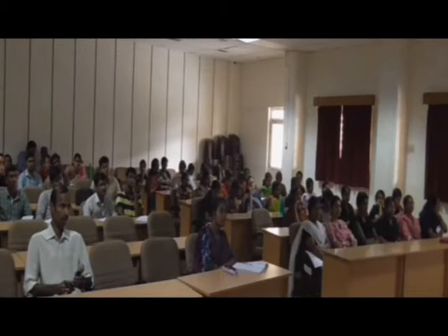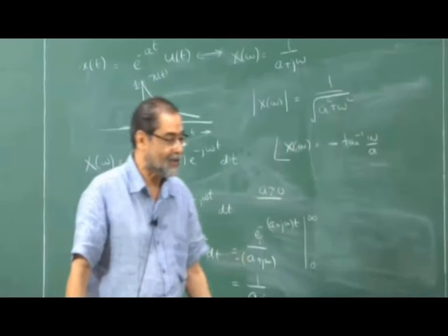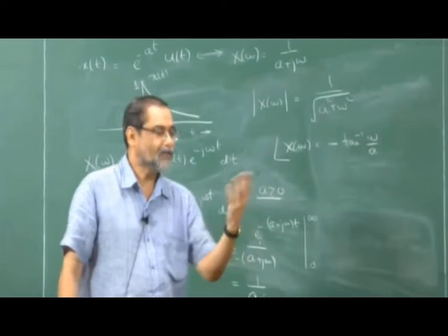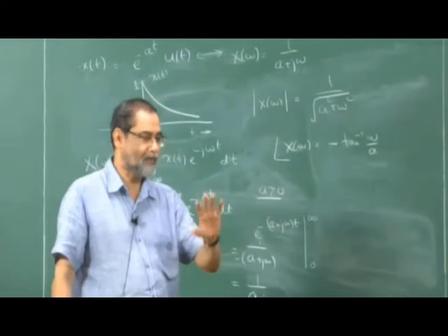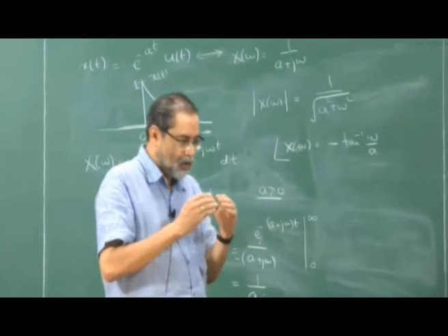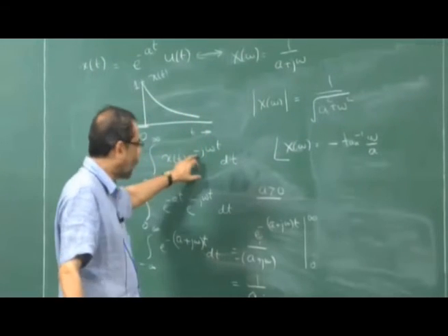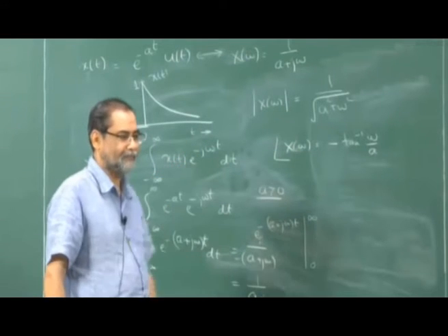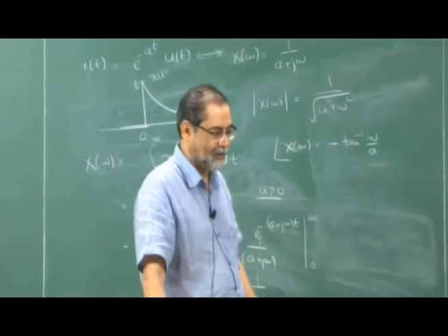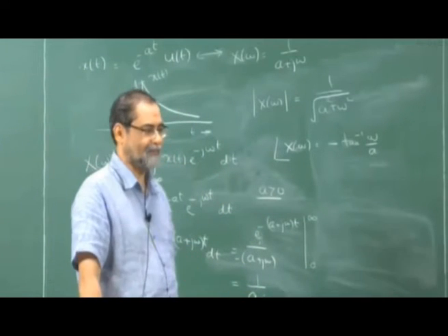That's also something, but when I come to discussing properties of the Fourier transform, I will show you that that is the Fourier transform of x of minus t, right. x of t flipped, x of t real but flipped, right. So to be consistent with Fourier series, I have to define the Fourier transform with a negative exponent here, otherwise I won't be consistent. Then whatever meaning I gave in Fourier series will not be carried over to this.